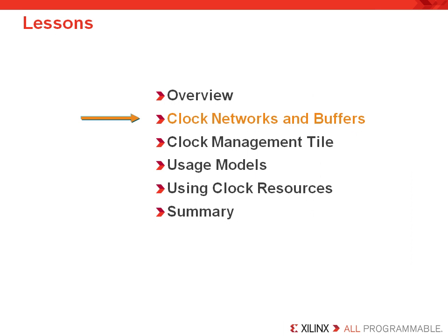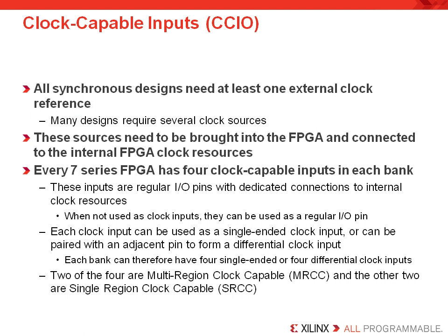Now let's have a look at some of the details of the clock networks and the clock buffers that are available to our customers. First, we need to know how external clock signals get into the FPGA. Well, all Xilinx FPGAs have clock-capable input pins. These are regular I/O pins in all respects, but they also have dedicated connections to the internal clocking resources, that being the clock management tiles.